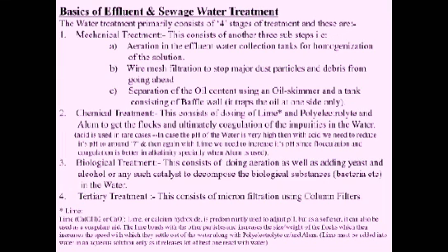Then the third stage comes, biological treatment. This consists of doing aeration as well as adding catalysts like yeast and alcohol or any other such kind of catalyst to decompose the biodegradable substances, bacteria, etc. in the water by speeding up its life cycle.